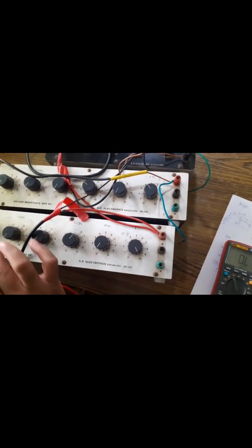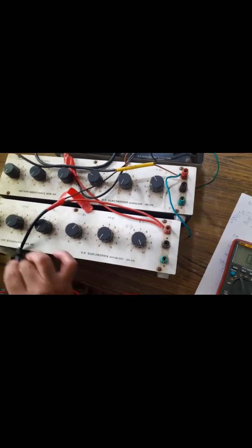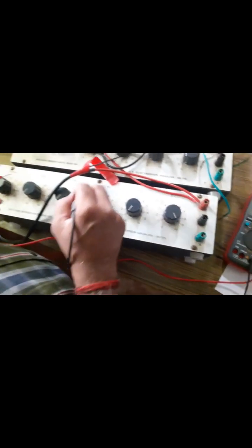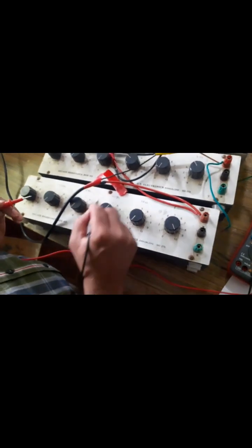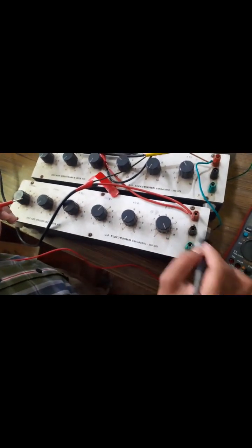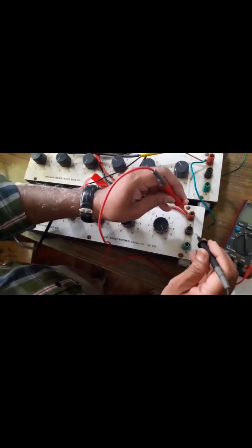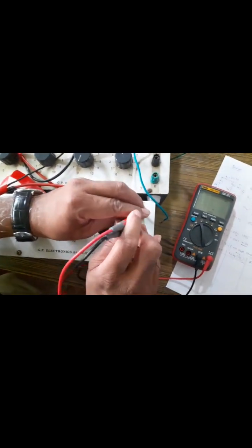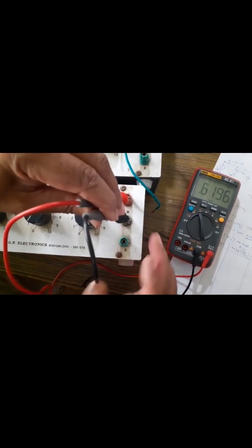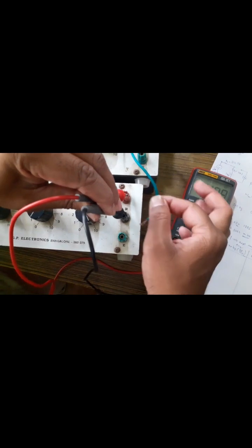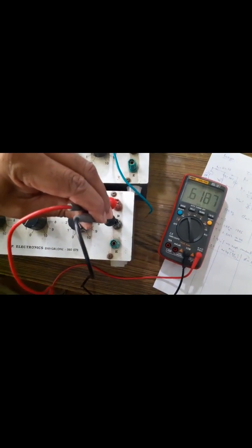Okay. Before starting the experiment, first you need to set the values, and according to our design R1 is 612.587. But if you simply take the help of these markings, you may not get the exact value. So use your multimeter to set the exact value according to your design, but make sure that one terminal of your decade box is free from the connection when you are using the multimeter.